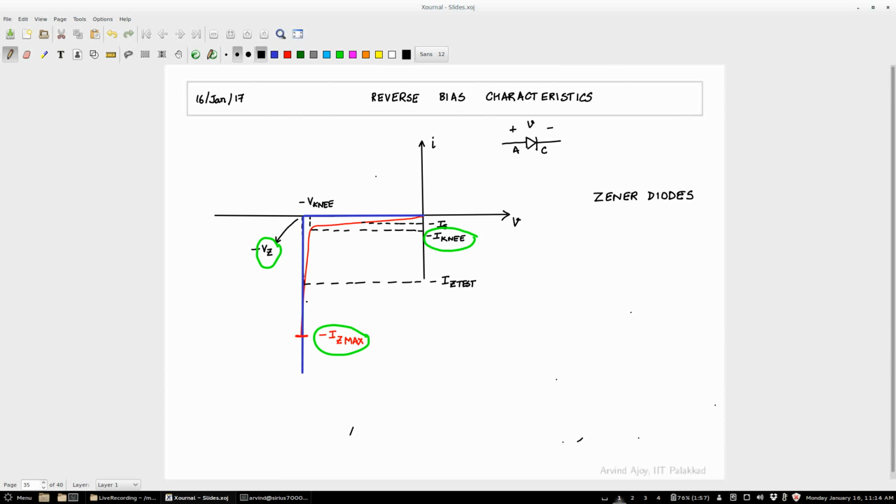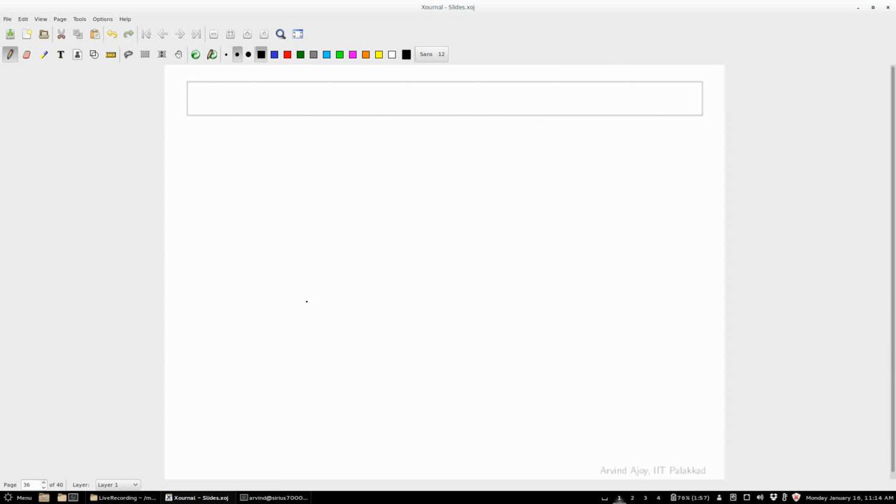Okay, you would see that when you are designing circuits, you can actually design things with very crude models, and it will be instructive once we do a SPICE class that you take the more realistic model and then check and compare it with what you have obtained using hand calculation, using a very crude design, and you will find that you are not too badly off. So design is very different from analysis, and that is something you have to keep in mind. Okay, all right. So now let's go to applications.